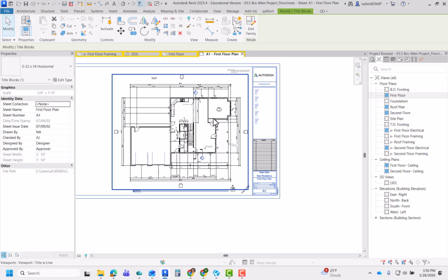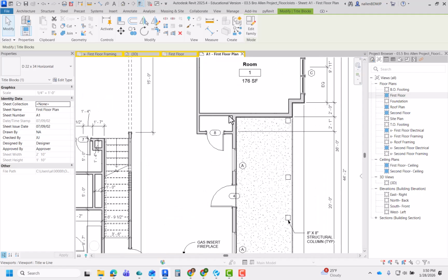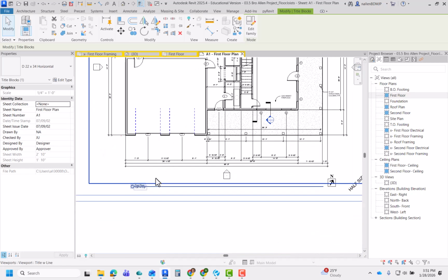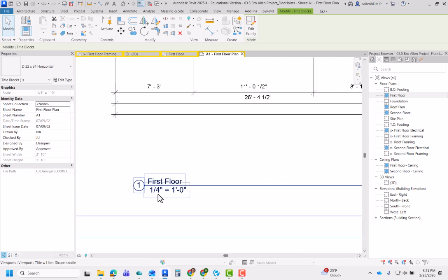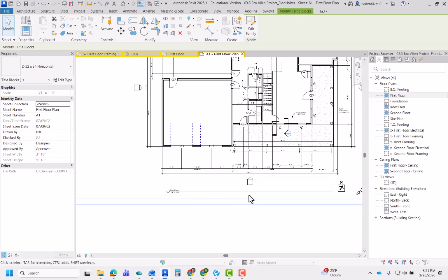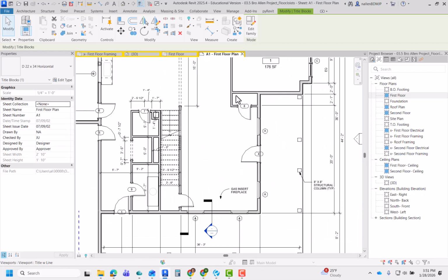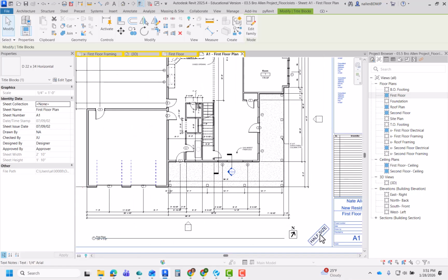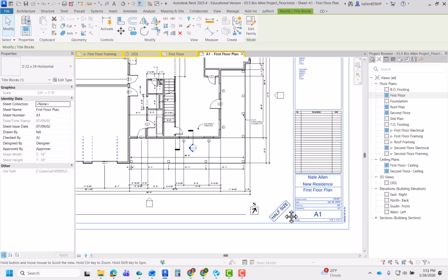Just to give you an example of why they might do that, this wall right here doesn't have any dimension to it. And if they wanted to know what should we build that to, or how long should we build that, without a dimension here, they might take a ruler or a tape measure, and they might measure that. And let's say that on a piece of paper, they measure that at 1 inch exactly. Well, if you understand how to use the scale here, every 1/4 inch is 1 foot. So we have 4 1/4 inches, giving us an entire inch, which means we've got a 4-foot wall. Well, if it's half size and they get that same measurement at just 1 inch, that's no longer a 4-foot wall. That's now going to be an 8-foot wall. So making sure to put this on every one of your half-size prints is really important.